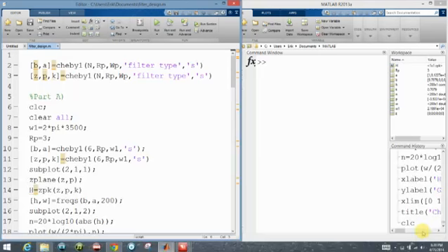Today I will teach you how to create a Chebychev Type 1 digital and analog filter design using Cheby 1 from the toolbox on MATLAB. Cheby 1 designs an nth order low pass digital Chebychev filter with R decibels of peak-to-peak ripple in the passband. Cheby 1 returns the filter coefficients in length n plus 1 vectors, b the numerator and a the denominator.